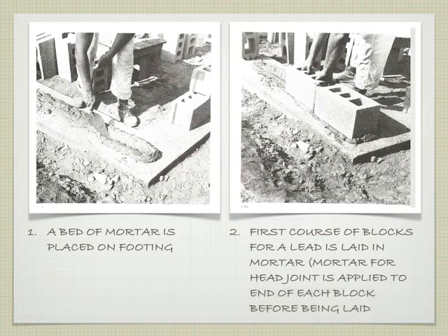So how do we go about laying these in the first place? It's a lot like bricks. Okay? So we place a bed of mortar on the footing. I know this is a little blown out picture, but you can look in the book or online and it's a little bit better. So we have our footing that's been poured.